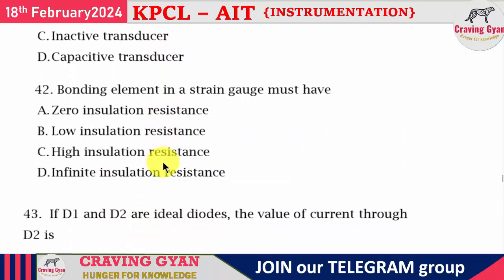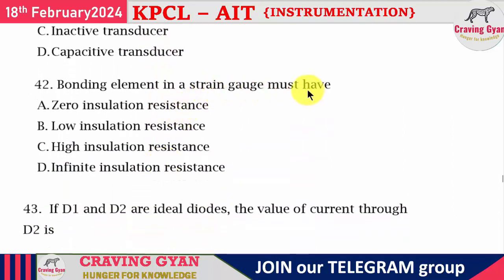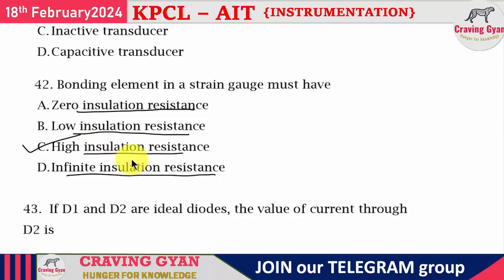42nd question, you see, the bonding element in a strain gauge must have. So the options they have given are zero insulation resistance, low insulation resistance, high insulation resistance, infinite insulation resistance. We are in need of high insulation resistance. Option C is going to follow. Even infinite is also not preferred, right? So far we have discussed the 42nd question.